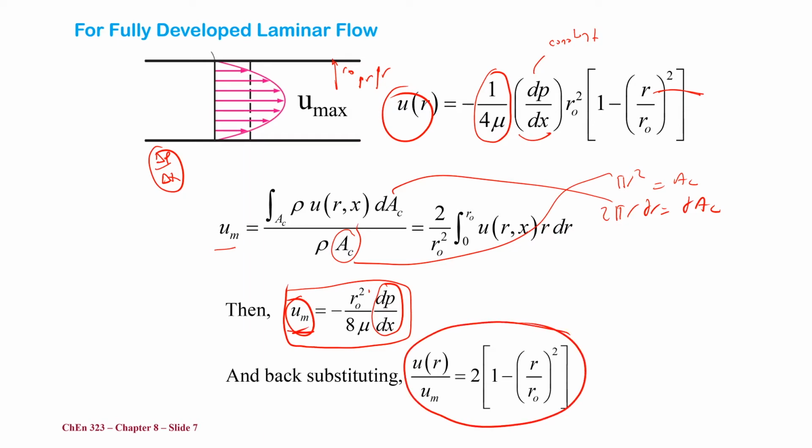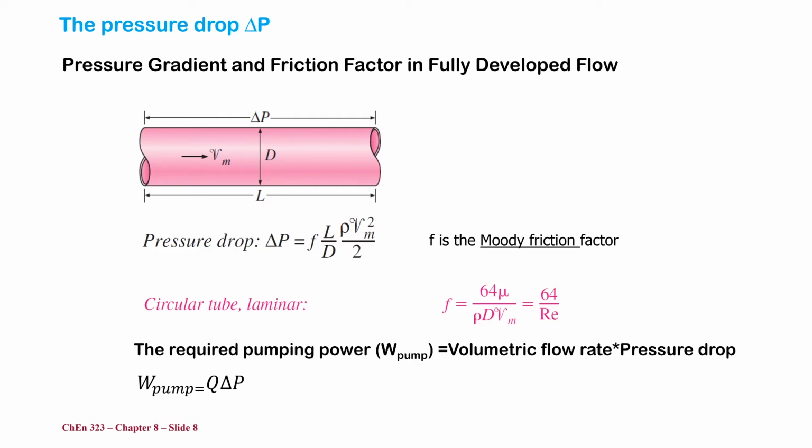relationship. Okay. So in general, whenever there is a fluid flow, if you have a finite viscosity, the pressure will drop because there are frictional losses on the walls. That means as the fluid moves from one side to another, it is going to lose energy. There's going to be a pressure drop. And the way to estimate the pressure drop is using the friction factor F. So this F is the friction factor.